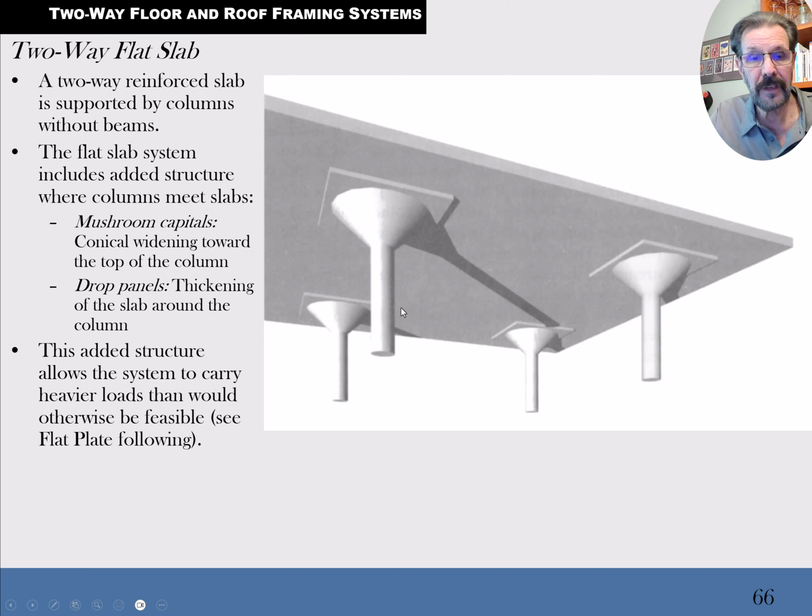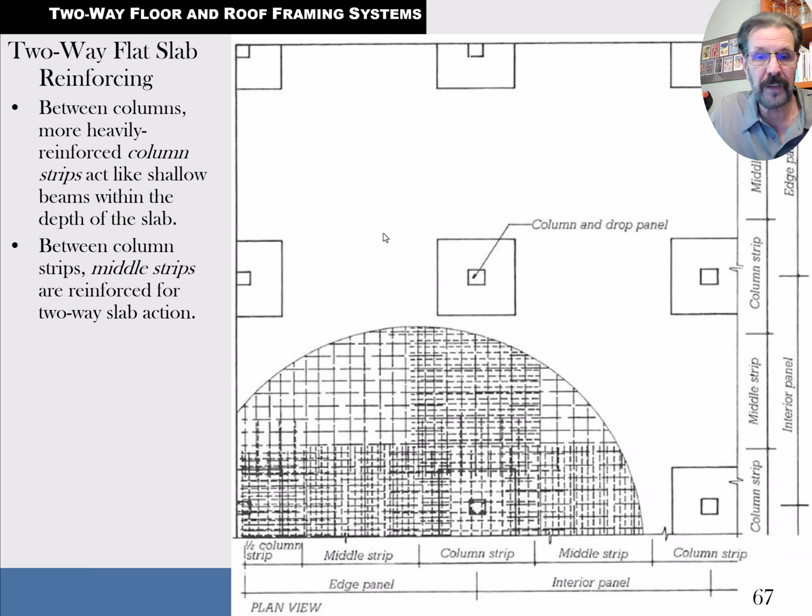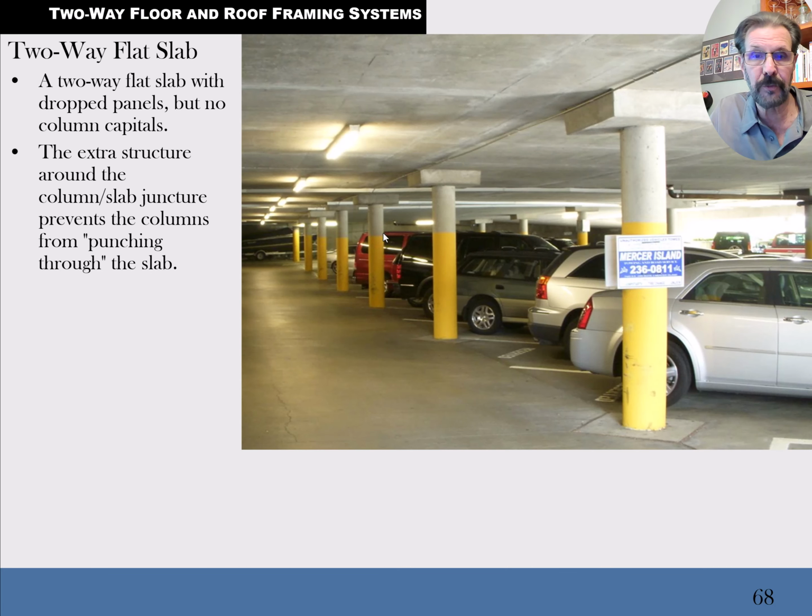So the comment, you can have both, one or the other or both, but they're giving you more room to transition to spread the rebar tentacles out into that flat slab up there. But it's considered a two-way system also. So what you see internally inside that flat slab is a heavy beam created out of rebar in the slab itself, basically. And so that's what's going on here.